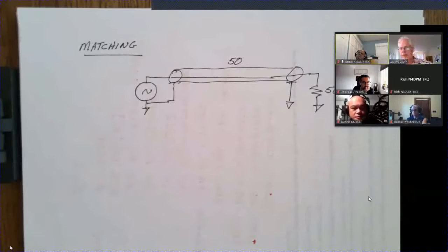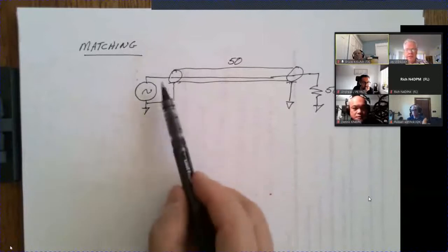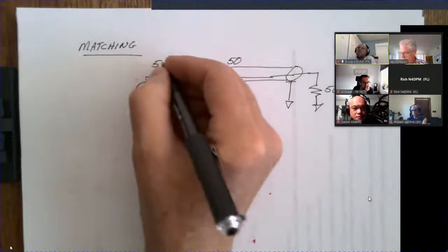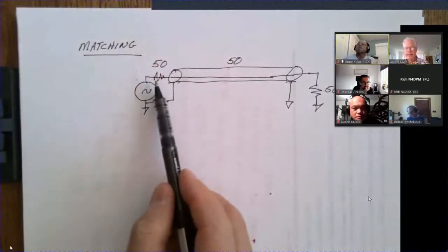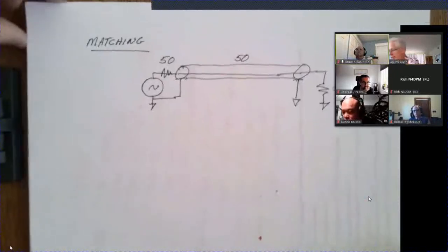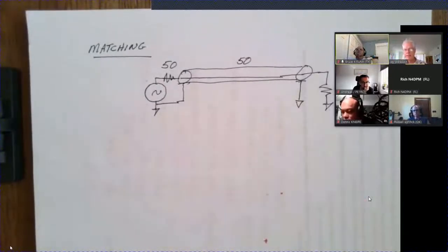This is the principle of matching. In other words, it turns out also your transmitter has a certain amount of output resistance, which is also 50 ohms. It expects to see 50 ohms. So if everybody is 50 ohms, everybody's matched. We're all going to dance together, and we're going to get the maximum power to the load. A lot of people think this is what really kills them as far as their radios getting out. Can be, but not always. So let's look at what matching means.